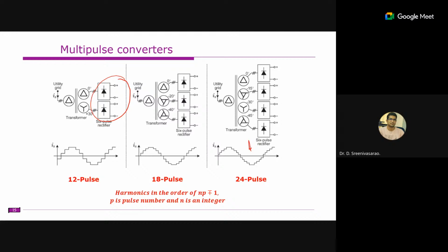So the currents it will handle are non-sinusoidal. When it is non-sinusoidal, the first thing is that we need to derate these transformers. You remember the K factor, right? In other words, you might have studied the transformer utilization factor, TUF. Accordingly, you need to derate the transformers because they are handling non-sinusoidal currents. And another thing is that if a small portion of DC offset is there, the transformer leads to saturation and draws more current for producing the magnetizing current, and that leads to lower efficiency.